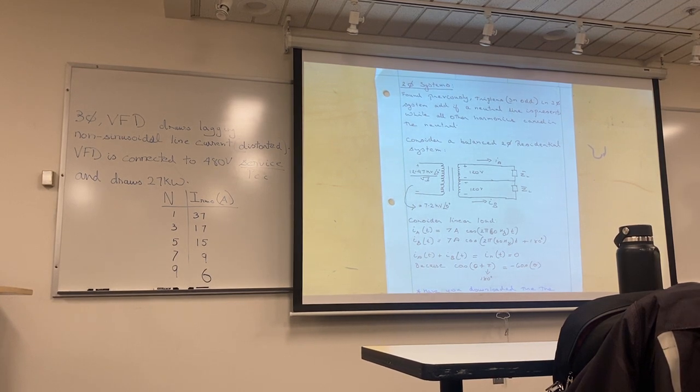So this line goes across your street, and from there I'll take a tap and bring it to a transformer that looks like a can on a pole, and it's got a sort of triangle here where it drops, and from here you will have a line coming, depending on your neighborhood. Old neighborhoods, it's just tapping from here and heading to your home directly. Newer neighborhoods, it's beneath the ground and then pops up at your house. But because I'm tapping it off a line, it's 12.47 kV divided by √3, which I just remember as 7.2 kV. So that's how you get the voltage to your home.